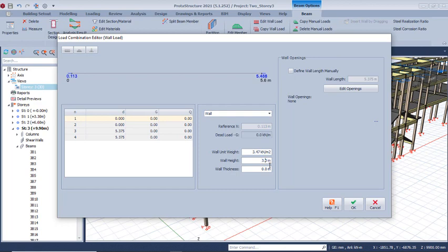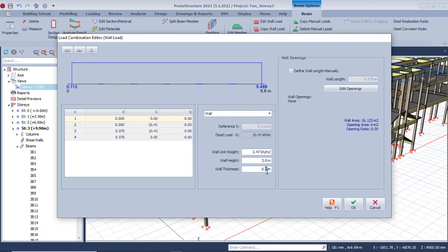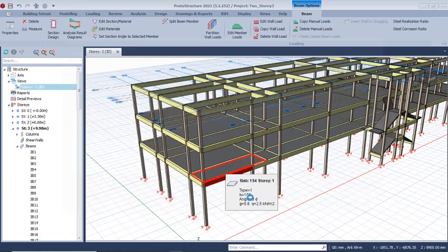3.0 right there. You ask me why is it not 3.3? It is because we have a beam depth right there. So we also have to key in 225 here. All right, so you have something like this. Just click on the okay option, so that we have our wall load just like this.